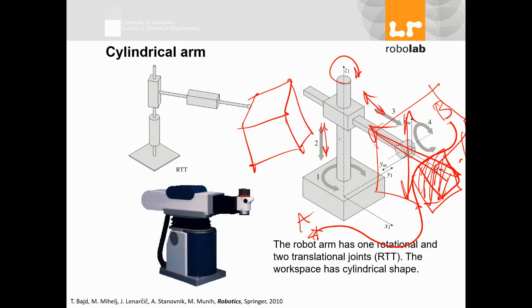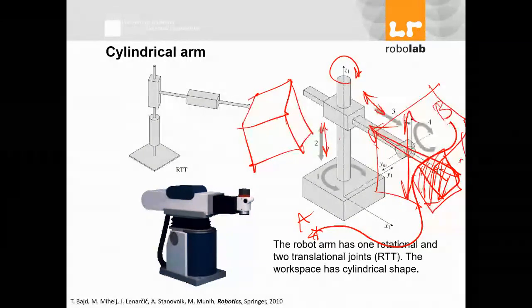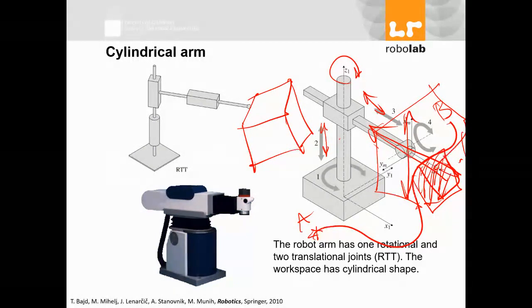So Jason says, doesn't speed depend on the mechanism driving? Yes, the drivers, exactly, such as ball screw, rotary gear, etc. You can make up for it with gear ratio. Yeah, I agree. As I said, if you focus on the force or speed, you have to consider dynamics. Dynamics means mass and force. We have to talk about mass, force, and even time. So M, F, and T.